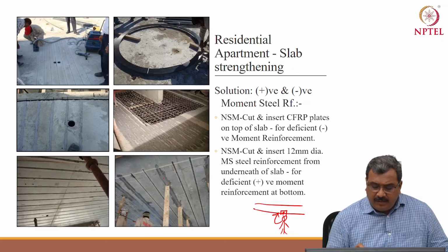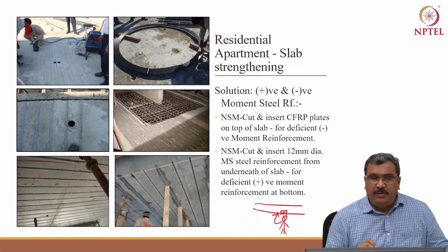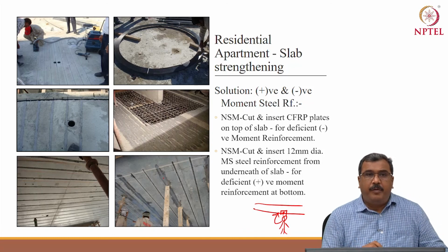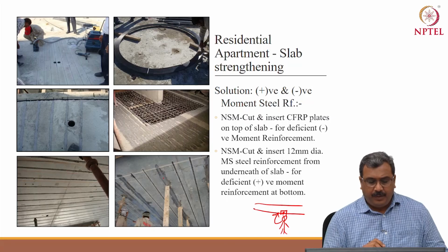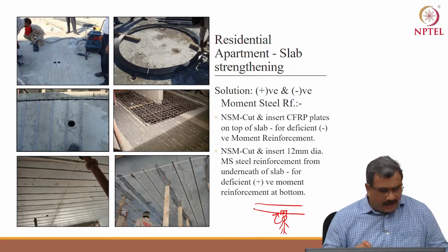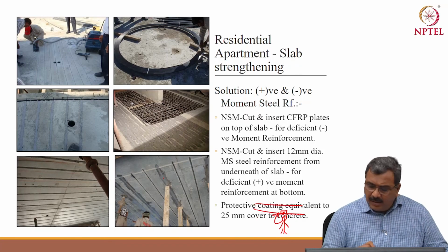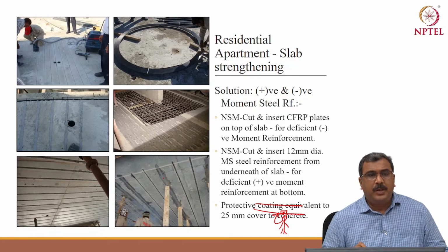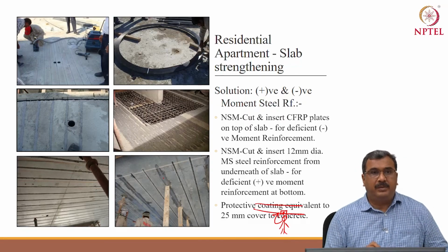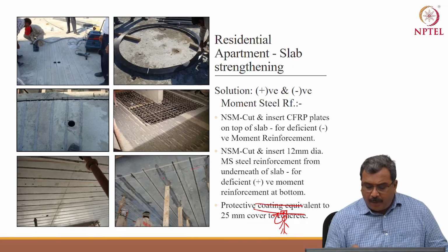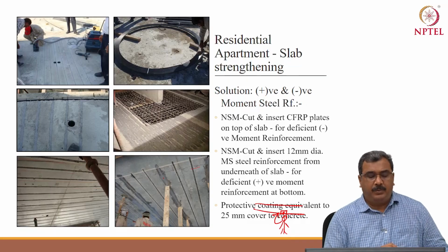The distance between each slot, the size of the slot has been designed as per ACI 440 NSM bar insertion parameters. Also, this entire area has been coated with a special coating which is equivalent to 25 millimeter of cover. So, you will get a proper cover for the entire area also.